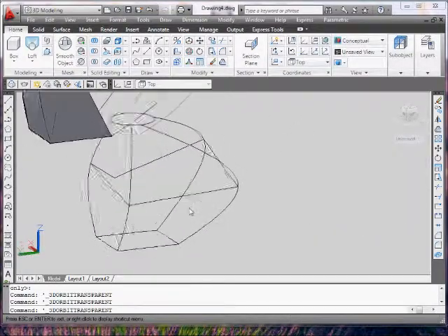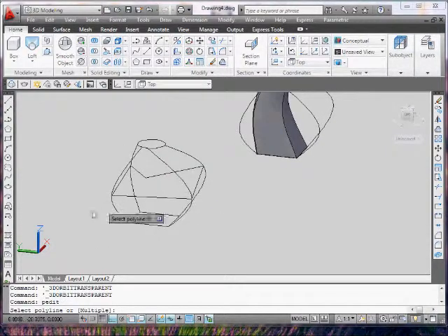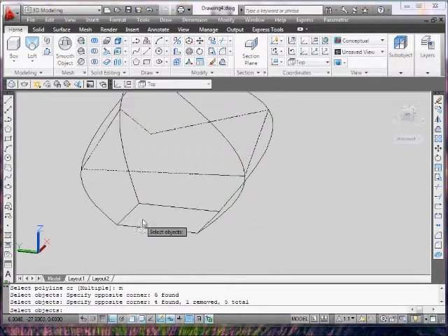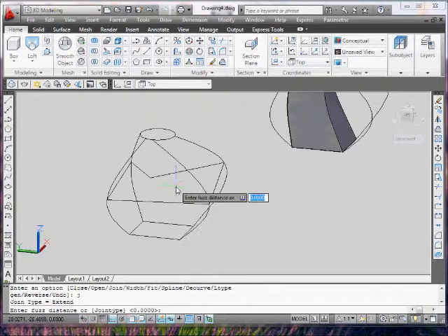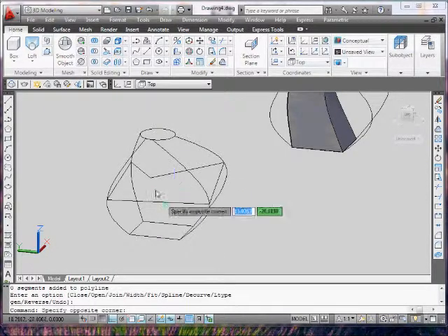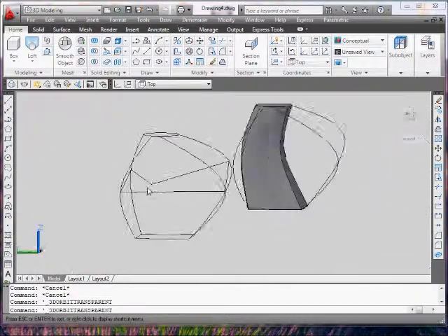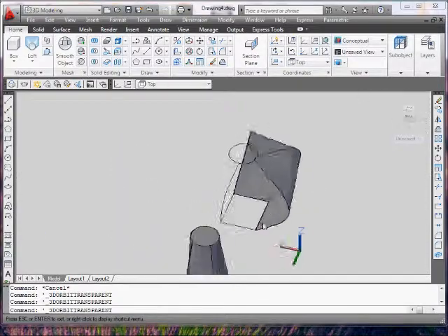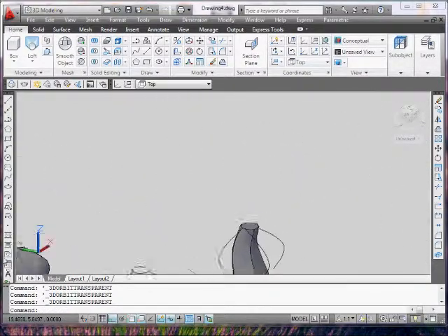And I'll actually go one more. I've got to make this a polyline, so I go to PEDIT, M for multiple. I select the inner square. Enter. Yes, I want to make it a polyline. Join them. Enter, enter, enter. That didn't work. Alright, we'll have to leave that one out. I don't feel like going through the whole thing. But with Loft, there's a lot of free play, and it's actually a lot of fun.